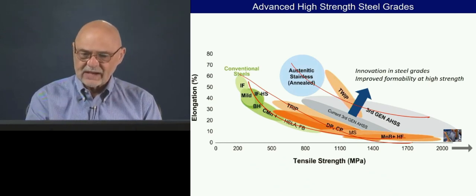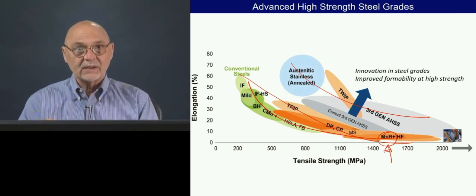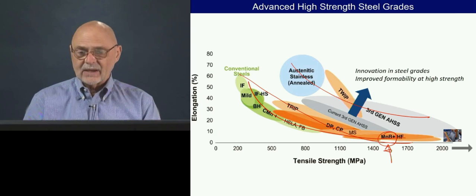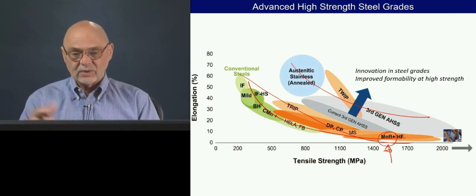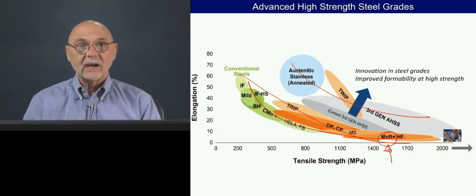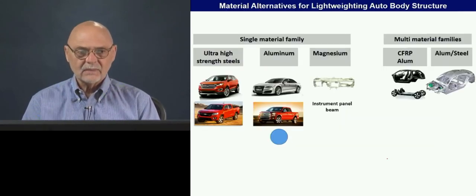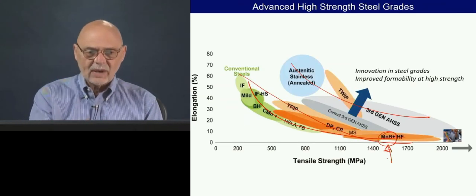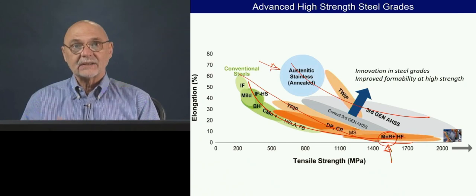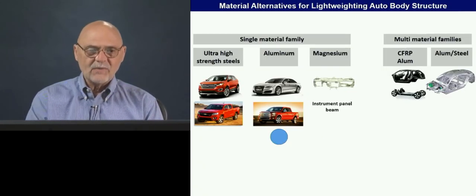And we saw last time that idea of hot forming a particular chemistry, boron steel, that we could form it hot, have really super good formability, and yet when it's cooled down, have ultra high strength as well. So you want to think particularly of this chart when you're looking at selecting different steel grades. Okay, so let's move on to